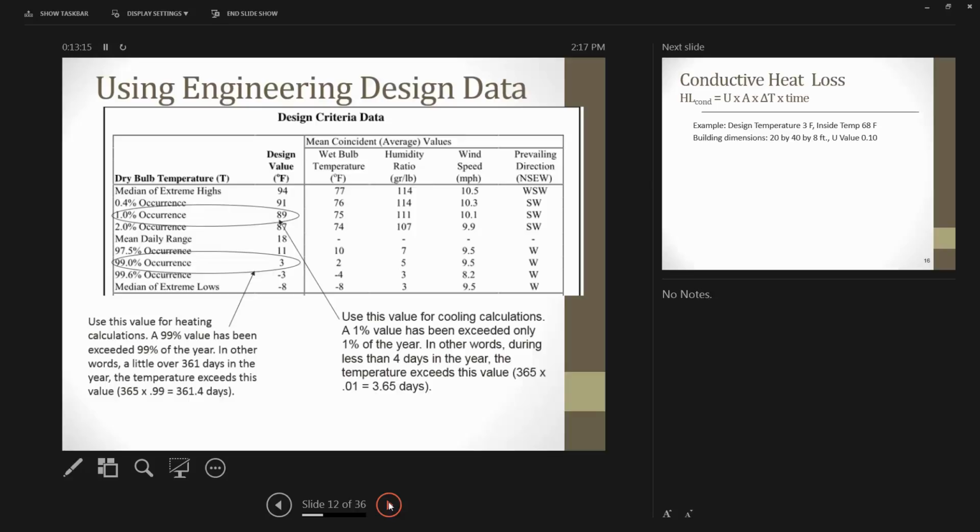which is interesting because it's based on the Manual J calculation in the code. It's the temperature that we have to use to design our systems. It'll make a little more sense, but I'll tell you right now that in my personal opinion, so you don't have to take it as fact or science, it's very, very inefficient to be designing a heating system to operate at a temperature that we are above 99% of the time. So we're really designing a heating system that's preparing us for the 4 or 5 worst days of the year.